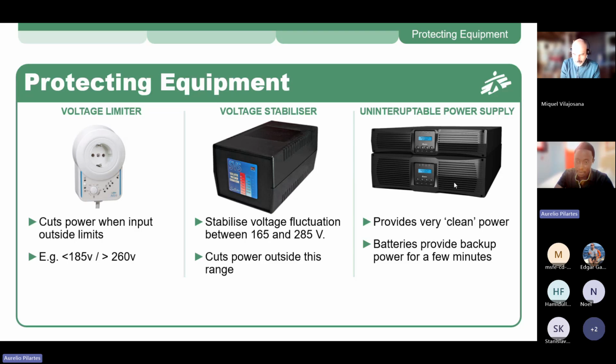So the UPS is more there to use when you switch from generators, or when you have, let's say, a problem with one generator. The time you switch from this one to the second one, the UPS will ensure you power and will allow the power to be continuous for the loads connected to it. So these loads will not feel this change or this interruption in the power supply.